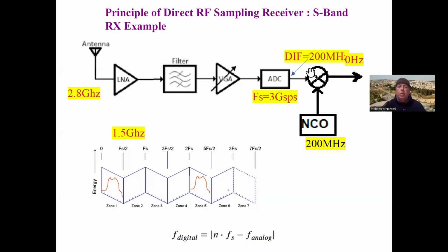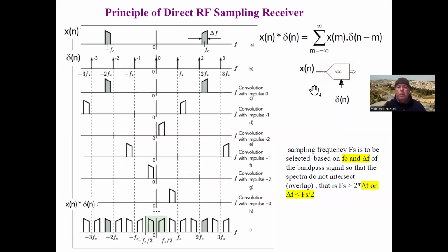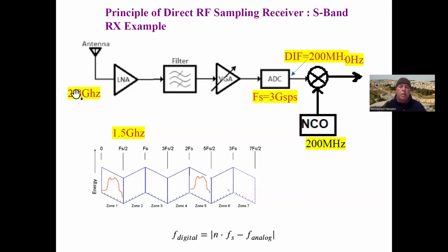The first one that will come, and we'll go through this computation later, is that your digital IF in here, if you take the FFT of this ADC signal without any filtering, is going to be centered at 200 megahertz. And that's going to be basically this signal here, except it's been synthetically frequency translated to the center frequency of 200 megahertz.